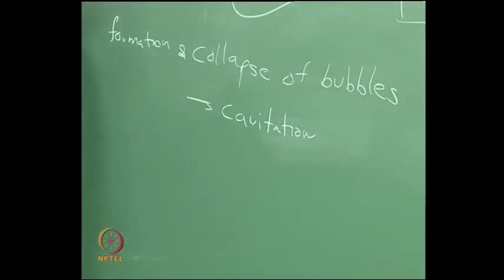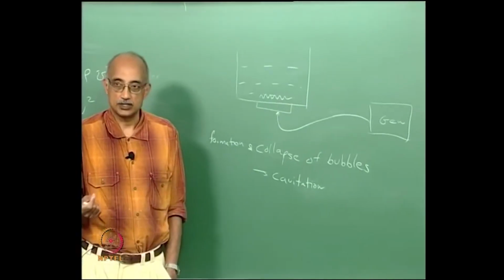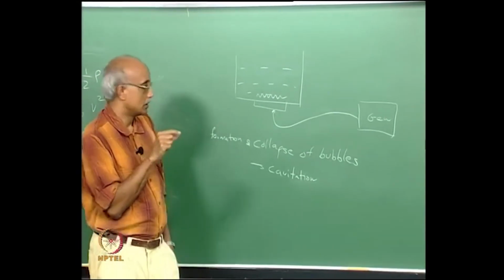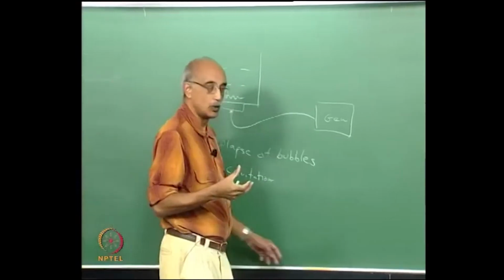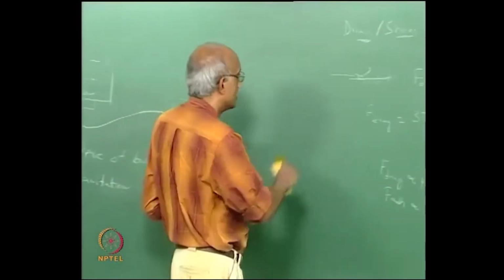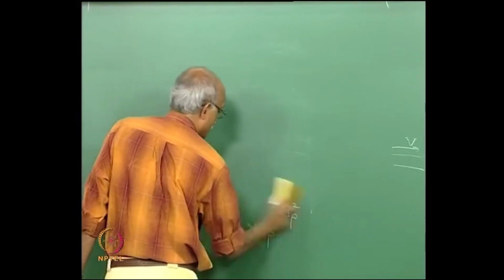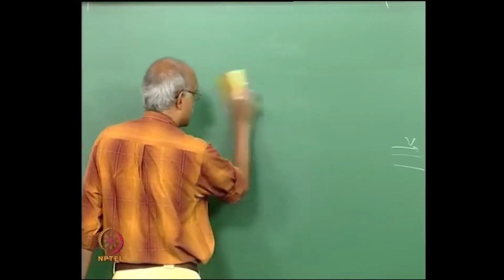The bigger the size of the bubble before it collapses, the greater will be the cavitation energy. So, if you use low frequency ultrasonics, the bubbles have more time to grow before they collapse. So, the cavitation forces are much higher in low frequency ultrasonics compared to high frequency ultrasonics.